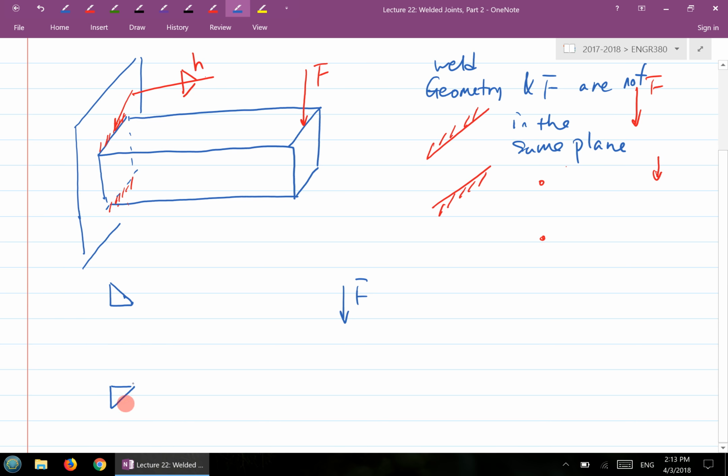For the welds, you see a shear force F going across the weld group. At the same time, you also see a torque generated by F, which is F times the total length L. If this is the centroid of the weld group, all you see is two types of loading: one is the F, and one is the M here. So let me redraw this here again.